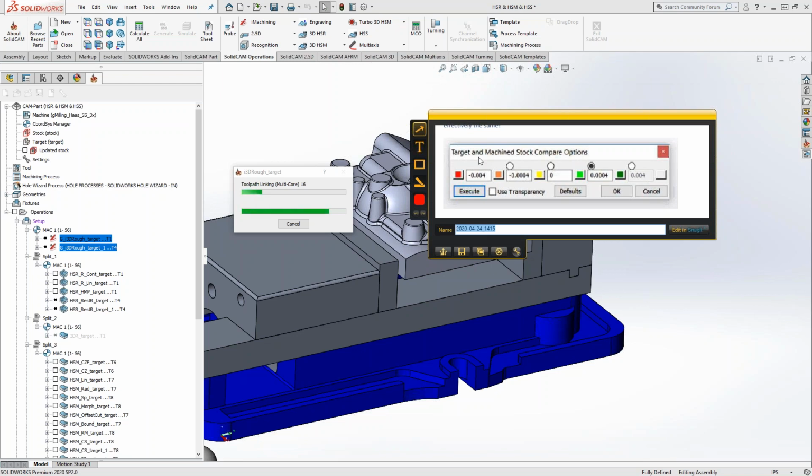So what I do is, for the good number, the yellow in this case, I would put 1/10, then the orange I would put at 1 thou, and my red I would put at 5 thou. That way, when I do my solid verify, I don't have to have a 4/10 accuracy, because it's going to take up a lot of time to create that model.